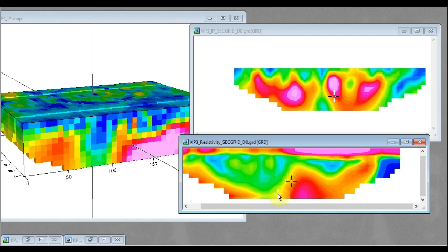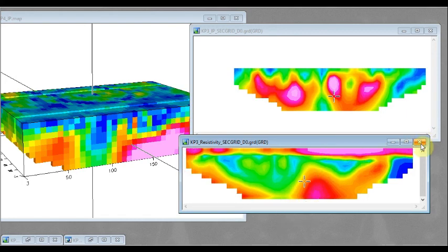Have you seen the same thing? You see? This continues this. And the surface effect is because of some of the lateritic materials at the surface, oxidations and all that. Definitely you see the high resistivity here. And that means the top actually contains iron which can conduct.